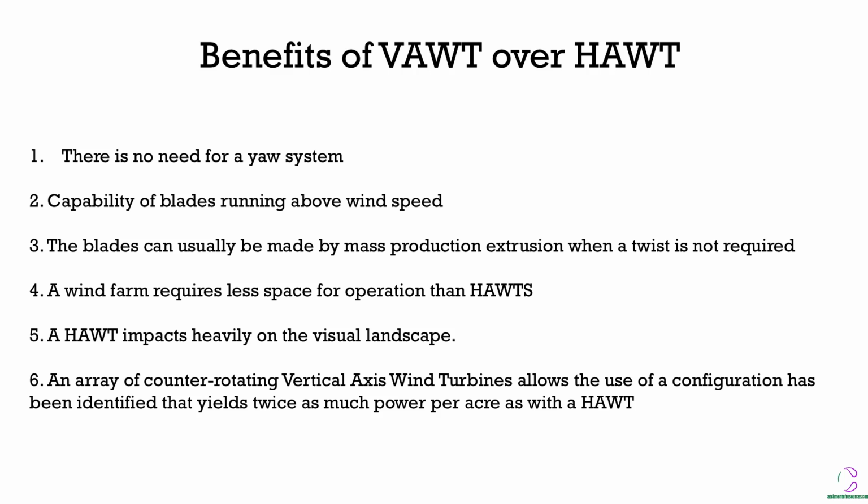For example, aside from the direct wind that is impinging on the airfoil or the cross section of the blades, you also have the effect of this wind after it bounces off the blade or cross section. There's an effect of wind on the blade itself, and also the turbulence that is created on the boundaries surrounding those blades. There are several ways that wind effects can ensure that the blades run faster than the wind speed of the environment. That's when you take into consideration the tip speed ratio.